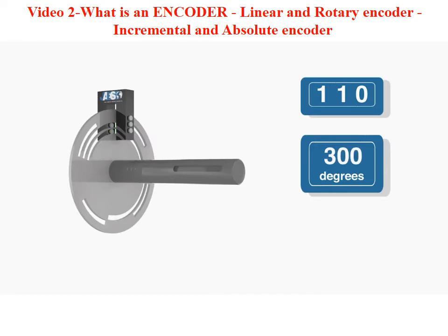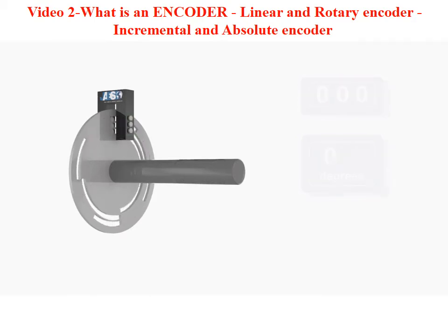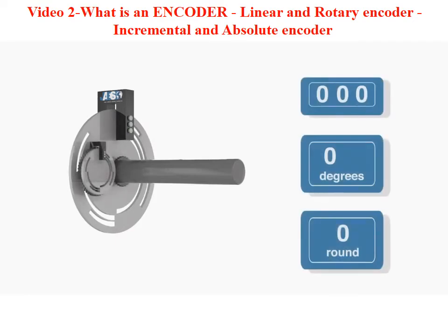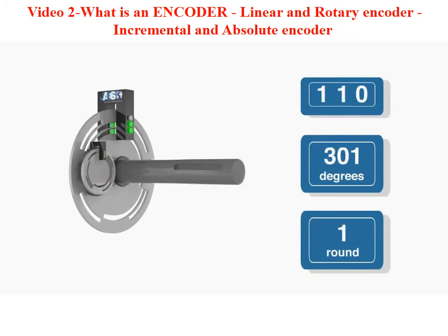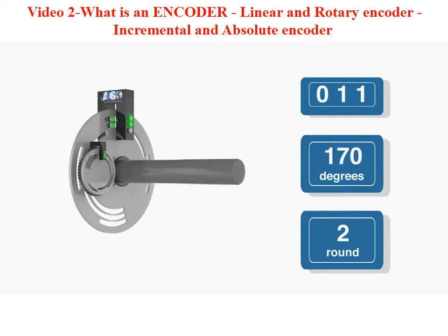position. If the power to the encoder was lost and the shaft was rotated, when power is resumed, the encoder will record the absolute position as demonstrated by the unique pattern transmitted by the disc and received by the pickup device. Absolute measurement encoders can be single-turn or multi-turn. Single-turn absolute encoders are used for measurements of short distance, while multi-turn absolute encoders would be more suitable for longer distances or more complex positioning requirements.